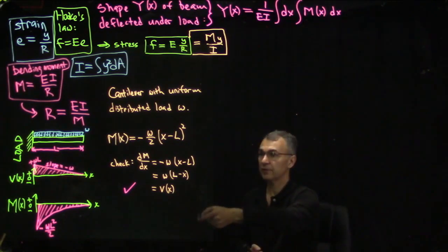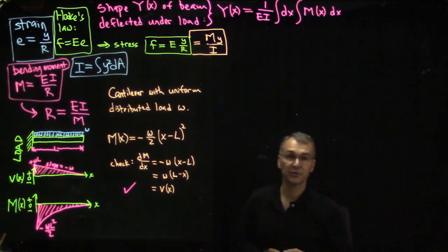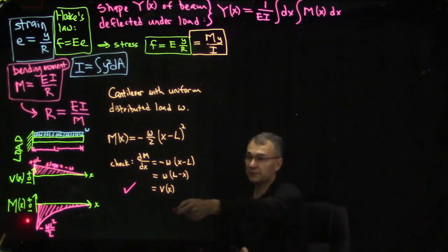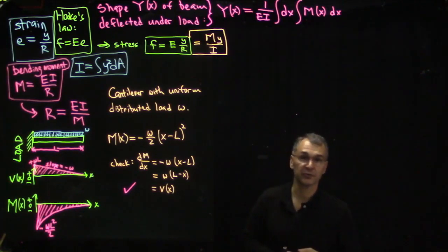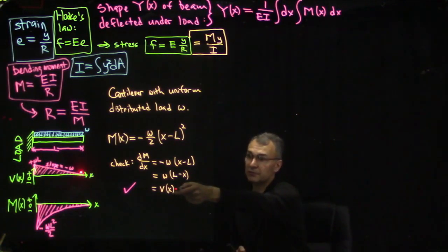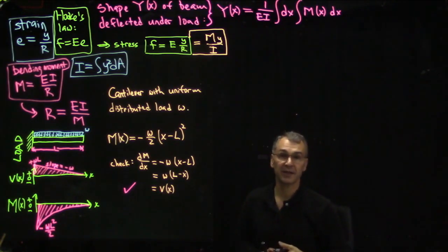Then we integrate that once to get the moment diagram. See, the load diagram is a constant, that's a 0th order curve. Therefore, the shear diagram, V, is a first order curve. Therefore, the moment diagram, M, is a second order curve. So we expect a quadratic curve, and we expect this maximum moment, WL squared over 2. It starts out at 0 on the right-hand side, and it's non-zero over here. It should be negative because a cantilever is frowning, not smiling. In other words, a cantilever is concave down, not concave up.